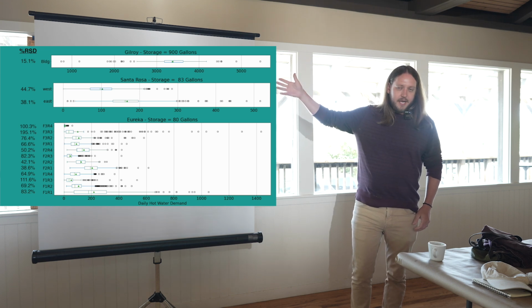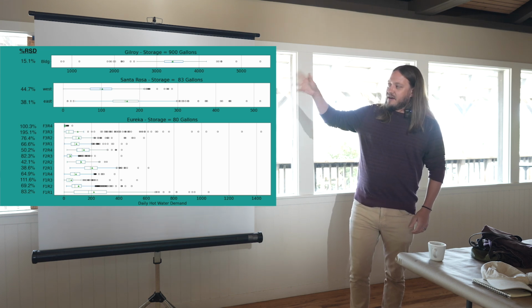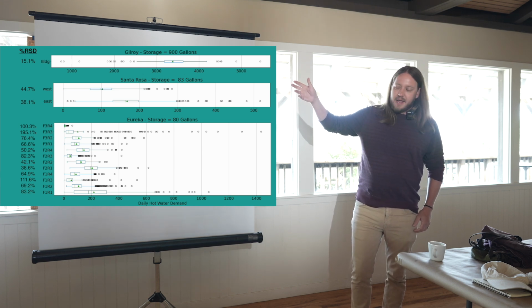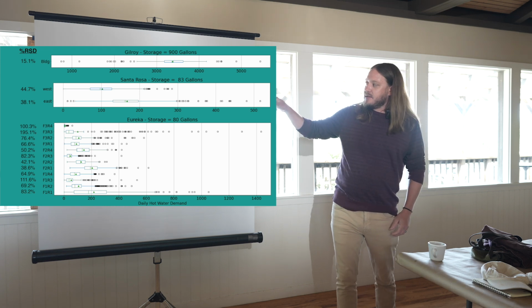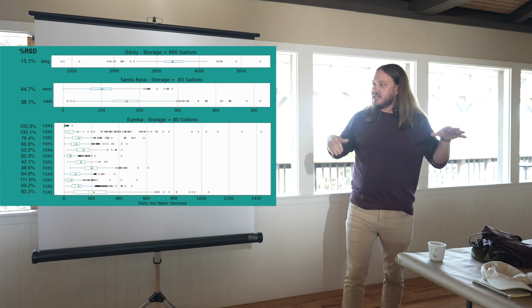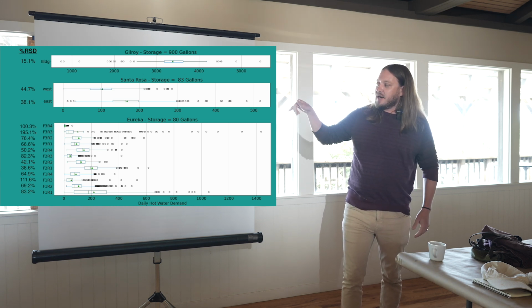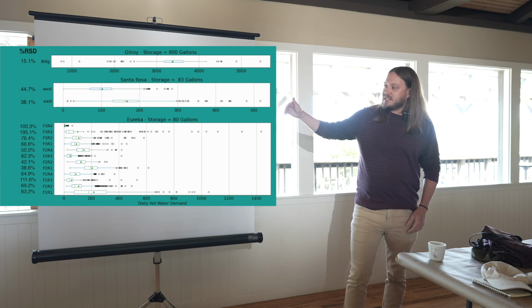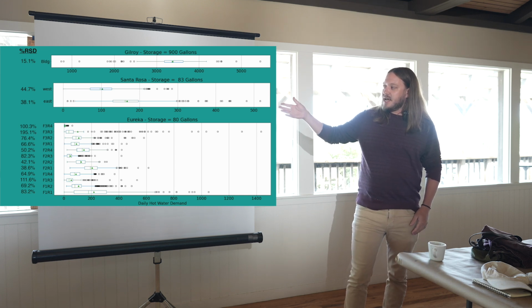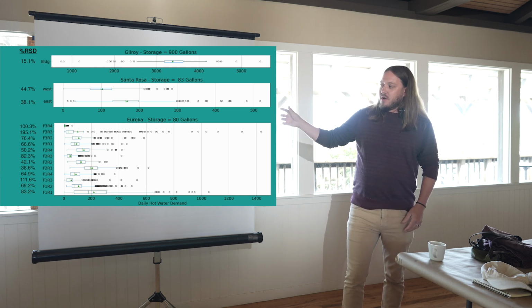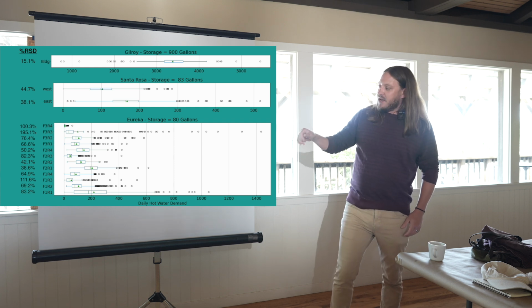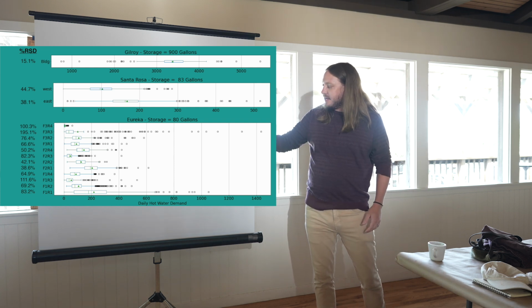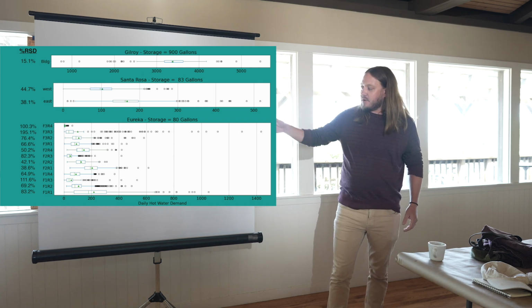Gilroy is a really large site, 75 units, averages about 3,400 gallons per day of hot water demand. And you can see, everybody evens each other's daily usage out. It's a lot tighter. If we go down to the next size system, which is much smaller, 7 units, 83 gallons of storage, we're down to about 100 gallons per day on average, but we have a lot more outlying days, right? We've got some days where we've got 500 gallons or 400 gallons, whatever.